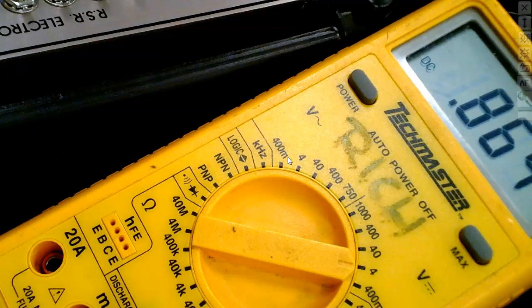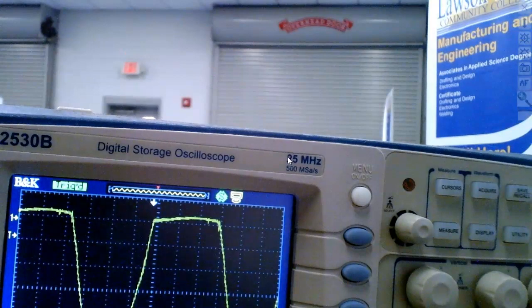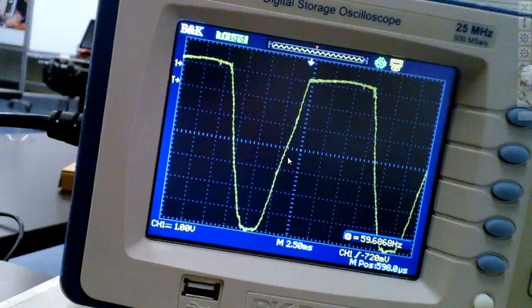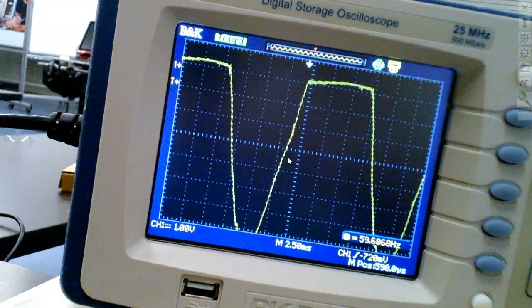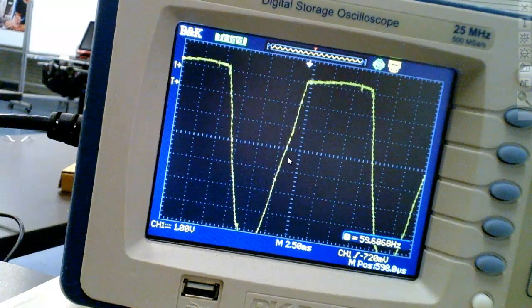So I'm over here looking at the resistor with an oscilloscope. The oscilloscope shows me what's there, right? You understand? So according to this, if I measure this with a meter on DC, we should measure the average of this thing. And it's not.